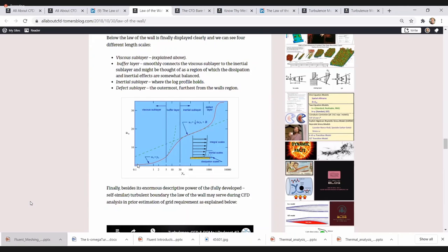It cannot get a Dirichlet boundary condition, which means that if we have some calculation where the physics effects are important, like drag or thermal issues, we need to use some kind of wall treatment. That's why you'd always see in the K epsilon many wall treatments. We're going to see them afterwards.